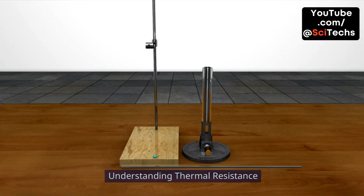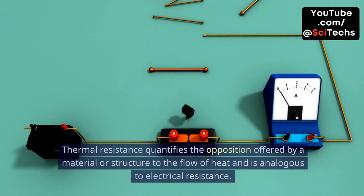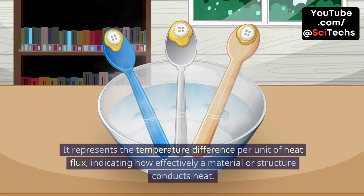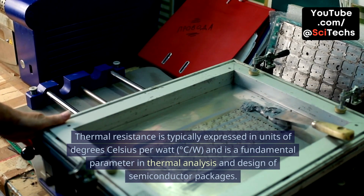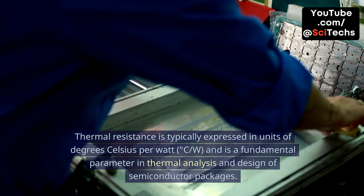Understanding thermal resistance. Thermal resistance quantifies the opposition offered by a material or structure to the flow of heat and is analogous to electrical resistance. It represents the temperature difference per unit of heat flux, indicating how effectively a material or structure conducts heat. Thermal resistance is typically expressed in units of degrees Celsius per watt (°C/W) and is a fundamental parameter in thermal analysis and design of semiconductor packages.